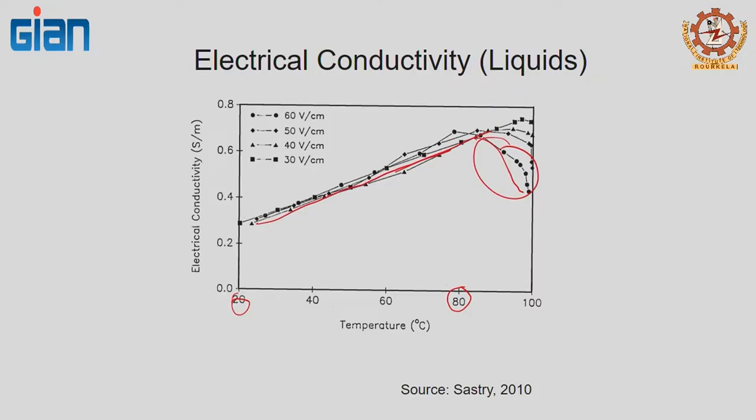If you don't pressurize it, then you're going to evaporate. So that's going to give you a different sense, false temperature readings. So this is where this data is not reliable. So you have to have a pressurized electrode or system to measure the electrical conductivity at higher temperatures.